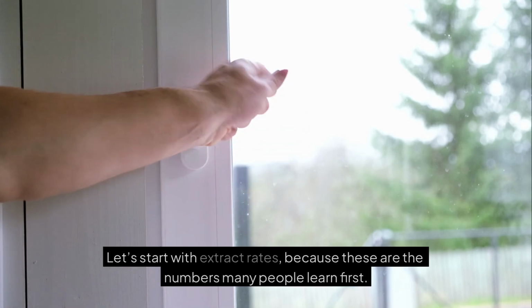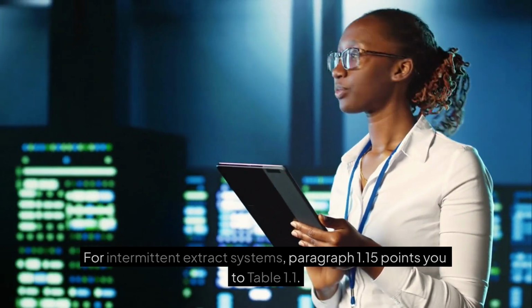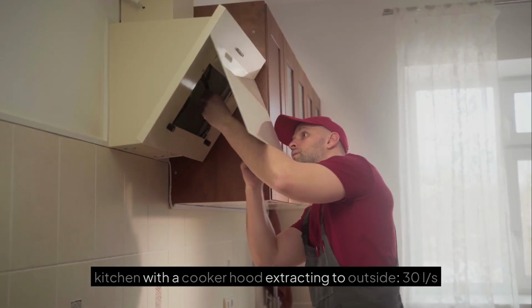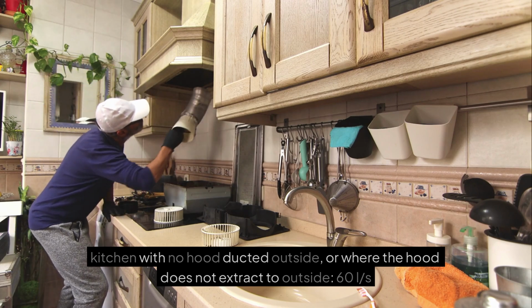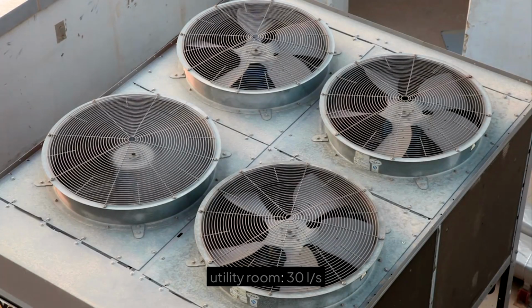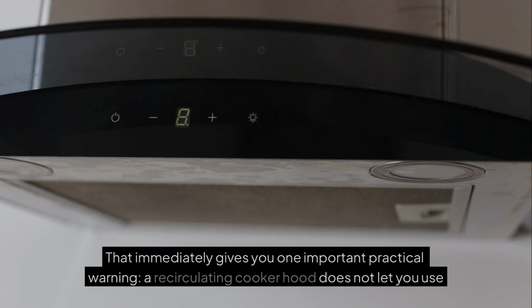Let's start with extract rates, because these are the numbers many people learn first. For intermittent extract systems, paragraph 1.15 points you to table 1.1. The minimum extract rates are kitchen with a cooker hood extracting to outside 30 liters per second, kitchen with no hood, ducted outside, or where the hood does not extract to outside, 60 liters per second, utility room 30 liters per second, bathroom 15 liters per second, sanitary accommodation 6 liters per second.